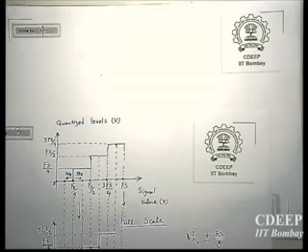See, quantization is not an explicit process. It happens implicitly. When you convert an analog signal to a digital signal, you implicitly do quantization. But if you look at the data converter architecture, you don't see any module called a quantizer. It is a virtual module, inherent inside the converter. What you are doing is sampling the signal, for example, comparing it with a reference value, and generating a bit at the output of the comparator. There is no quantization process here.